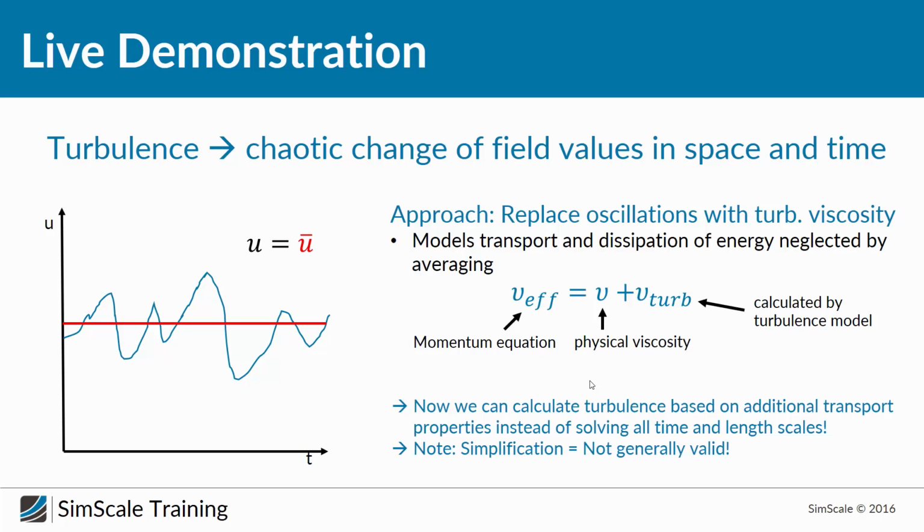And it's not generally valid. And to be honest, if you would ask someone who's really involved in turbulence research, he would say this is not true. But the simplification is still good enough for most of the cases and allows us to simulate also complex high Reynolds number, highly turbulent flows with a limited amount of computational capacity.